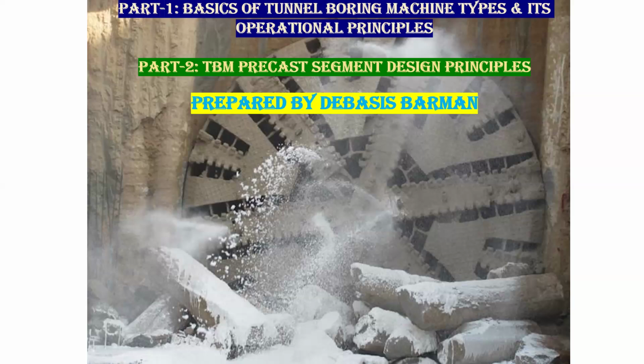If you compare the progress of a TBM and conventional tunneling, in very competent rock conventional tunneling can reach 2 to 2.5 meters per day. But if it is very favorable ground for the TBM, you can reach 20 meters, sometimes 25 meters per day. Since it is mechanical excavation, the excavation and the support installation are done simultaneously. And in TBM tunneling, there is no concept of primary support, only the final support.